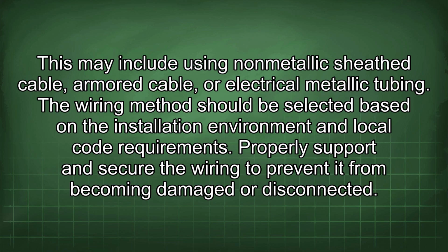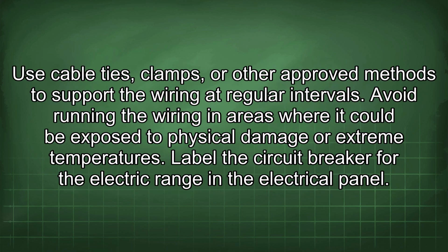Properly support and secure the wiring to prevent it from becoming damaged or disconnected. Use cable ties, clamps, or other approved methods to support the wiring at regular intervals. Avoid running the wiring in areas where it could be exposed to physical damage or extreme temperatures.